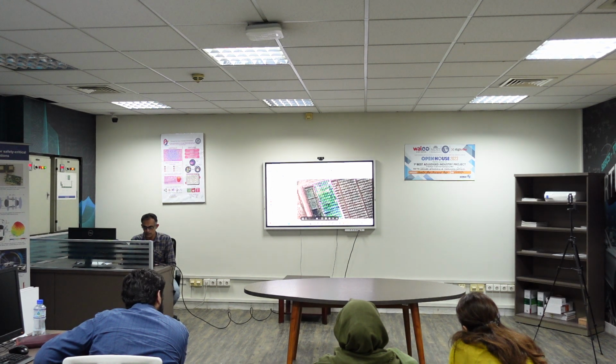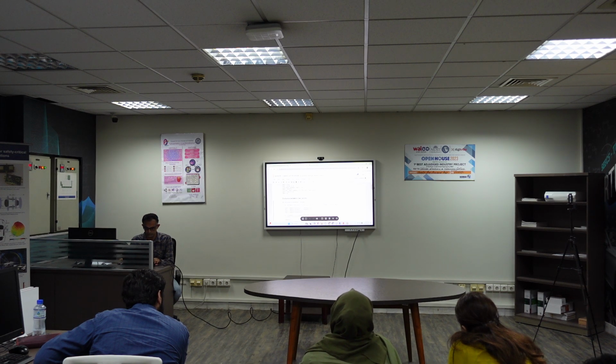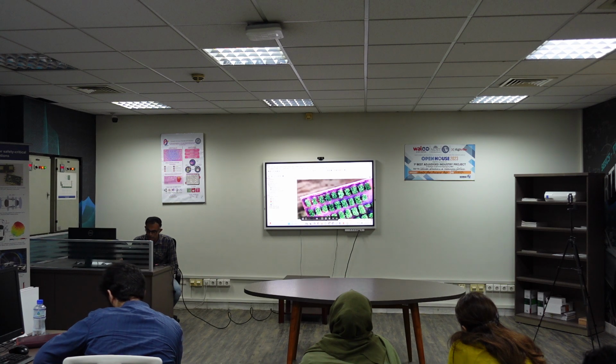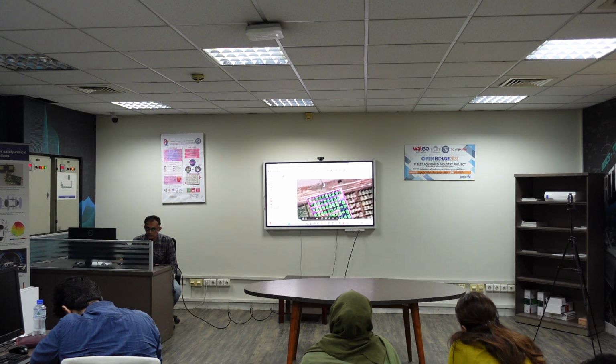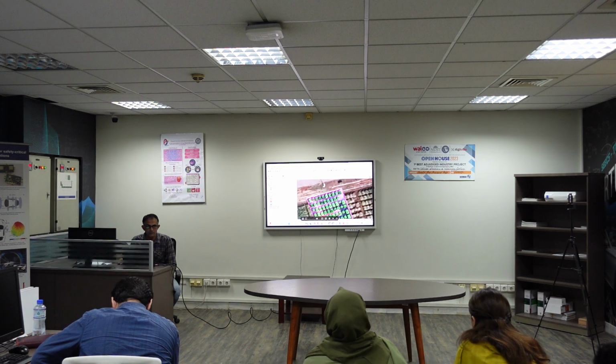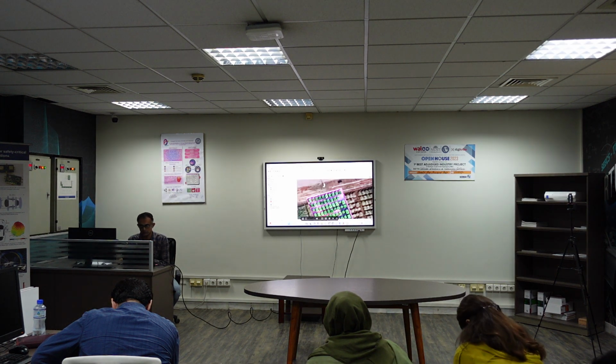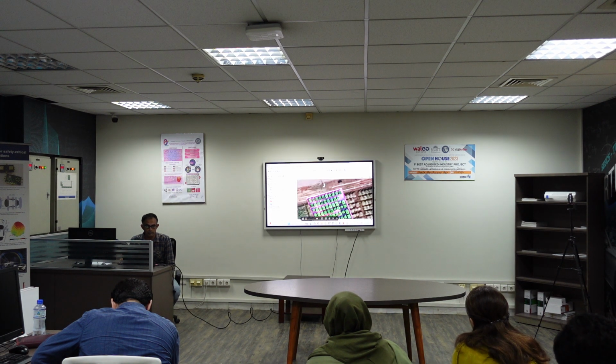So for handling that, I have written a code for that purpose. But I will show you how it is helpful, and what would be the input requirements for that. What we want is a grid layout in a way that the first box comes here, then the second box comes here, and then the 11th box comes here, and so on. So we want a spacing between the grids, which QGIS by default does not offer. We want a sequential pattern, because we also want to label each of these plots.